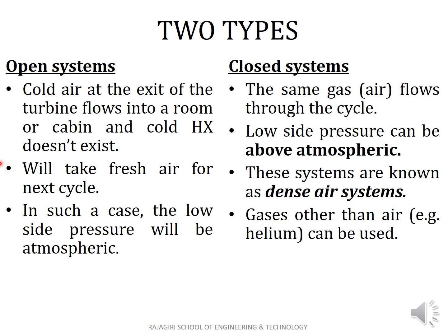In such a case, the low side pressure will be atmospheric. In an open system, the low side pressure is atmospheric. There is no low side heat exchange process, so there is no heat absorption process in an open cycle. This cycle is used in aircraft refrigeration.